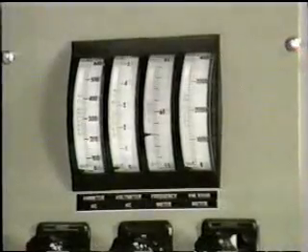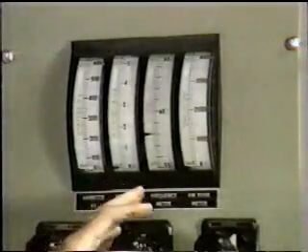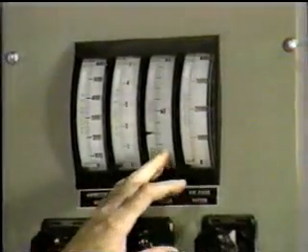The potential transformer is also very accurate but steps up or steps down generator output voltage as opposed to amperage. Voltage from the potential transformer is sent to the voltmeter, the watt var meter, the frequency meter, and synchroscope.